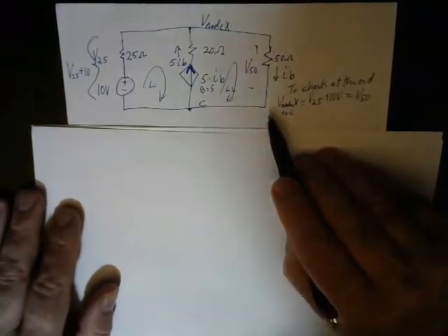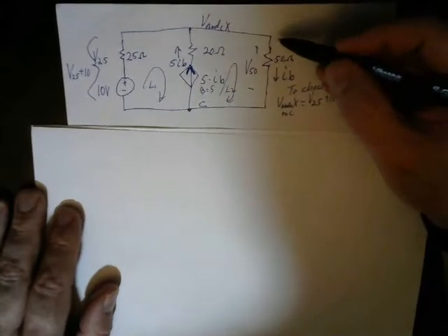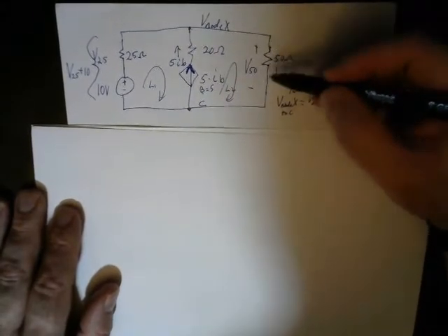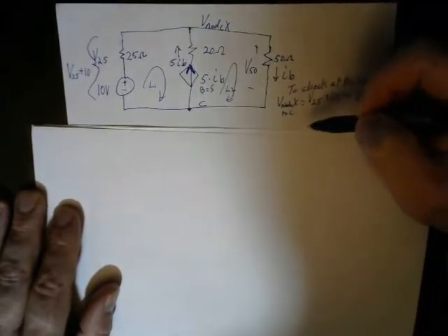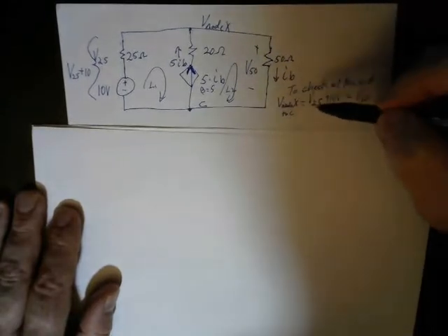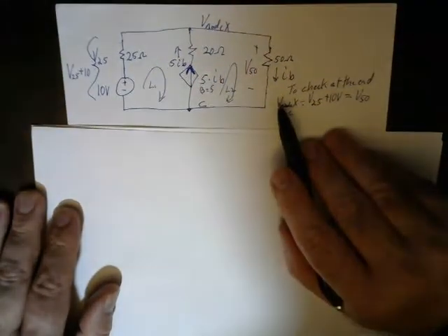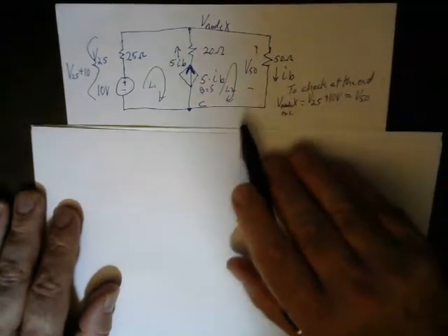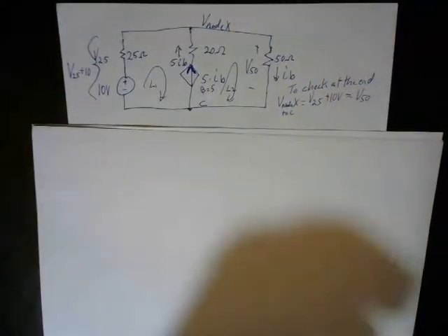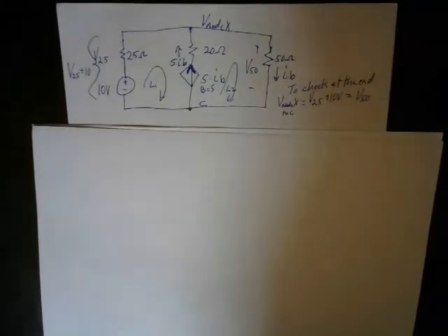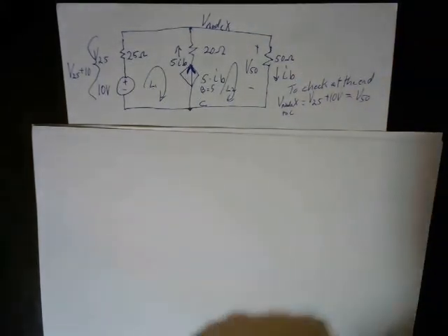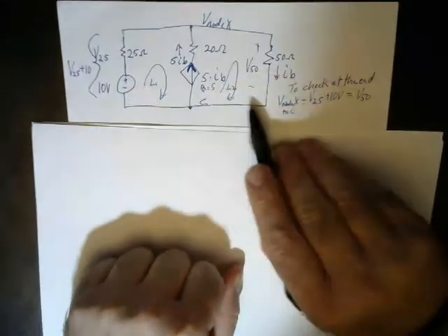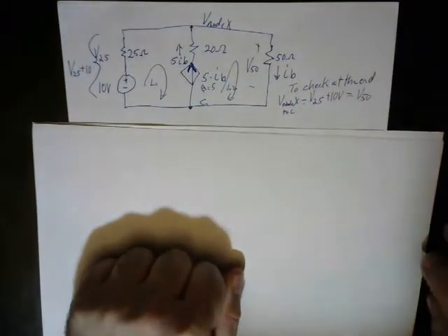You can analyze these circuits by putting a fictitious source somewhere, like across these terminals, and generating a current. And with that fictitious source, you can analyze the entire circuit, and then set that source equal to 0 and see what it is. But you'll see that the current always goes to 0 in the absence of an independent source. So you might want to try that. You might want to analyze the circuit this way and then take away the 10 volts and see what happens.